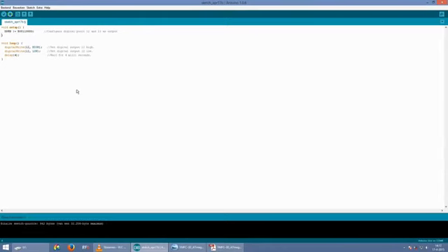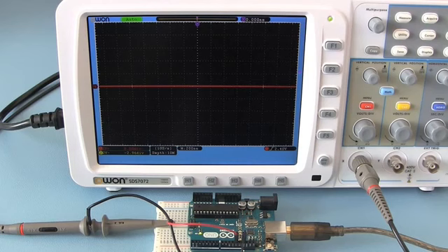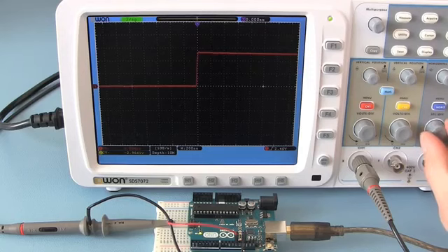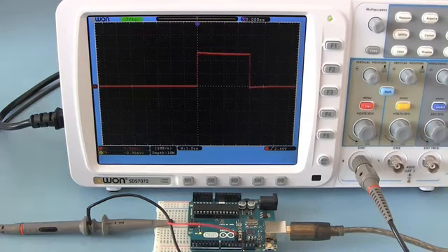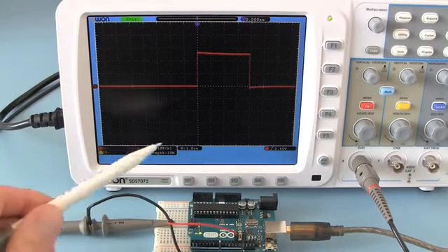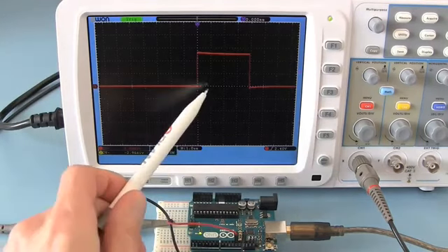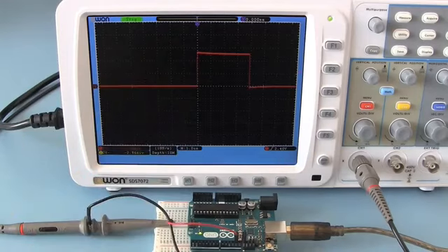You might think that setting the port high and low produces a very short pulse. Unfortunately this is not the case. The overhead, or extra code lines, that come with the digitalWrite command use an enormous amount of clock cycles. I set the scope for 1 microsecond per division, and as you can see, the pulse is 4 microseconds long.